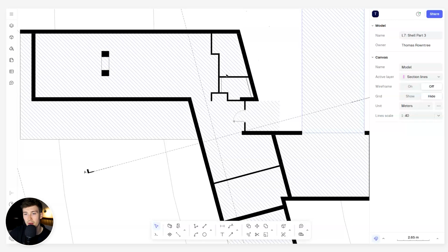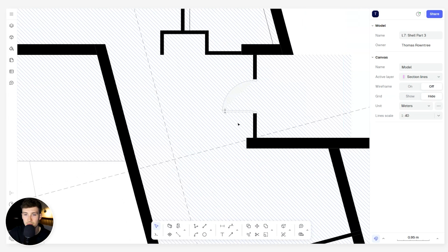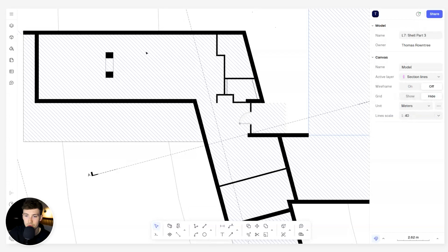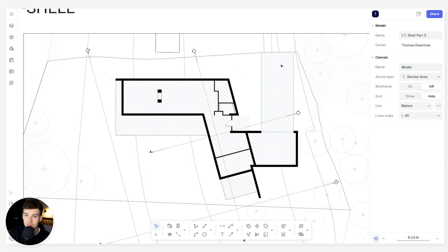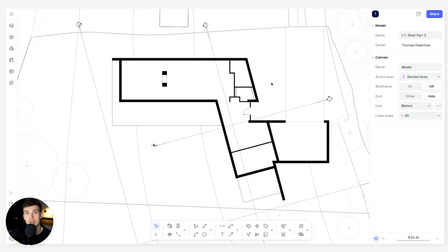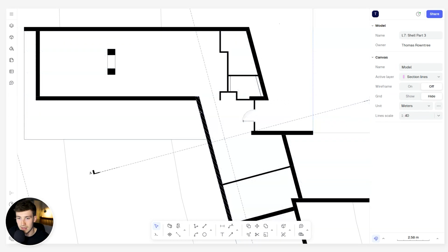Now the way that I want this floor plan to work is, as you enter this opening space, I want this to be an arrival point, as I've mentioned in the previous lessons. I want this to be a point where you obviously have these options of moving in different directions, but you also have this sense of arrival and views over the landscape. So as you enter in this back more public zone where you have the driveway, obviously it's quite a closed area because of the nature of the landscape. But as you enter through the space, I want there to be glazing that opens up these views from the moment that you arrive into the property.